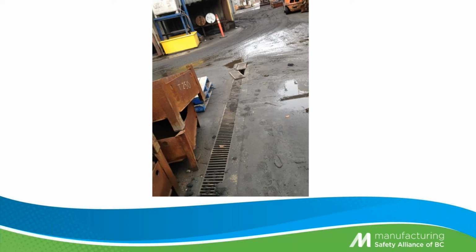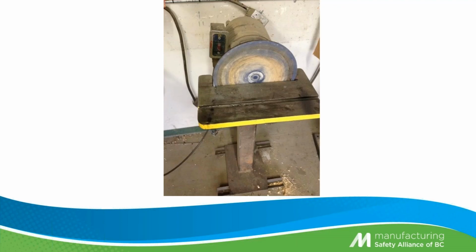The next one, we've got a grate missing. So this is a tripping hazard, or potentially a forklift can get a wheel stuck in there and possibly move a load or offset a load and potentially lose the load on the forklift. Here we have a sanding wheel, and that is the manufacturer's switch. I don't know what they were thinking. There's the potential that someone could cut themselves on that, and that's self-explanatory, the hazard. The corrective action here is they moved the switch to underneath the cutting table.